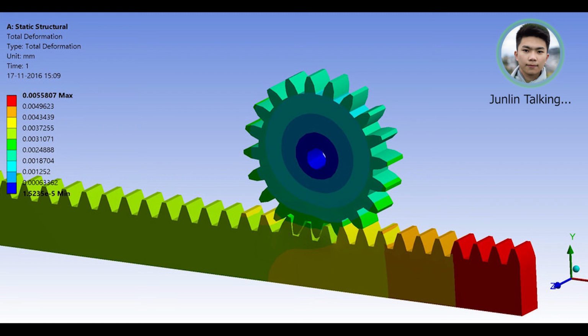The gear-to-gear set uses a 12-tooth, 20-degree gear mated to a 60-tooth, 20-degree gear, which gives a speed reduction of 5-to-1 and increases the motor torque by 5 times. The same 1020 carbon steel is used for these two gears. The calculation yielded a safety factor of 1.91 for the smaller gear.